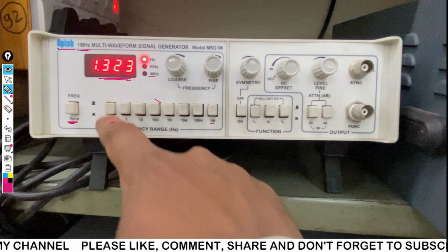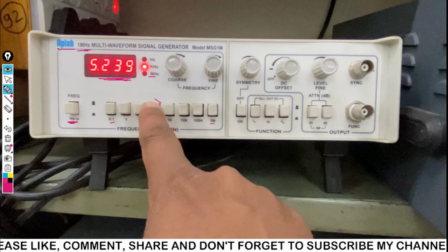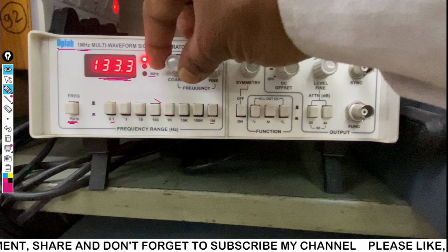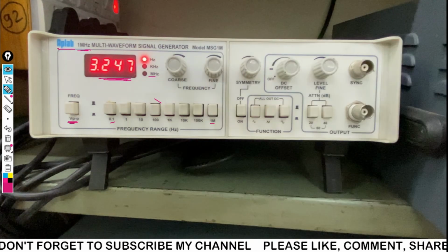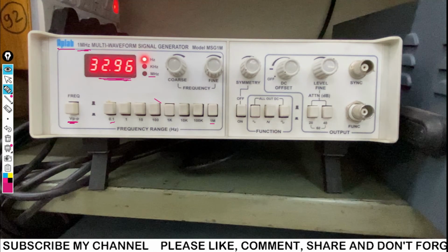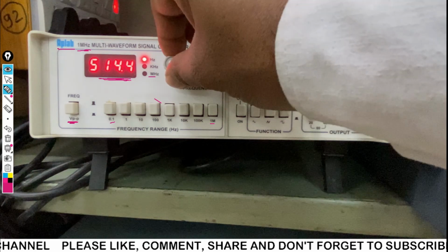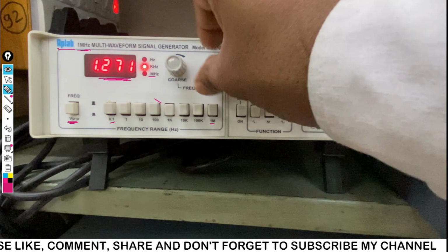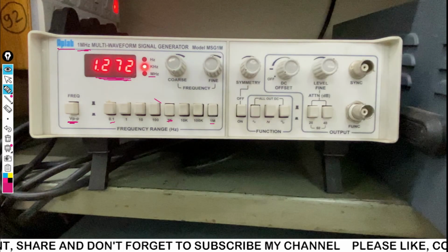You can see here, if I press the 1, we'll have 1.323 hertz. If I press again the other button, it will show a different frequency. This is due to the coarse and fine. If I make the coarse very small, approximately equal to 0, and suppose I press 1k, you can see the minimum shows 32 hertz, and if I increase it further, at the maximum it will go towards 1.3k. So I press 1k, it was showing 1.3 kilohertz.